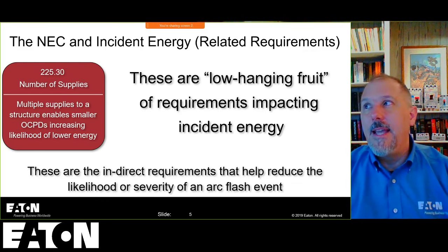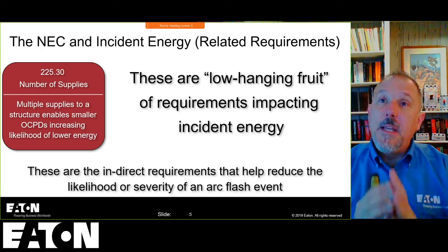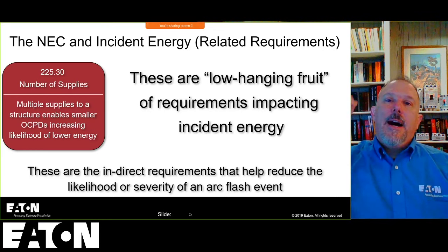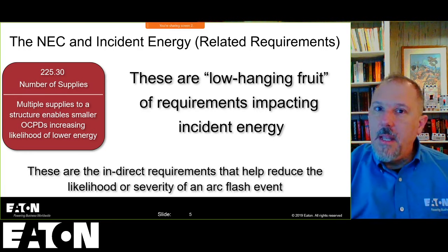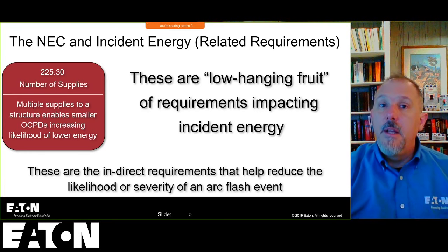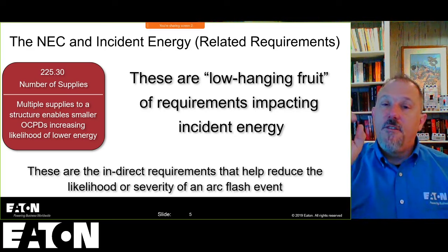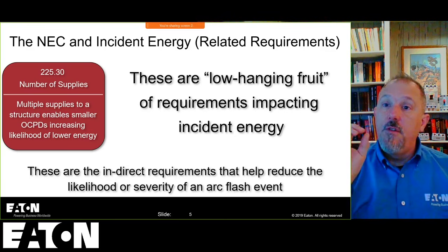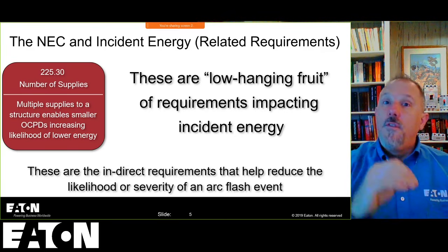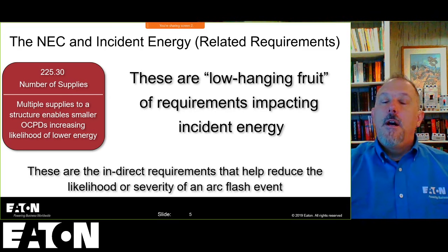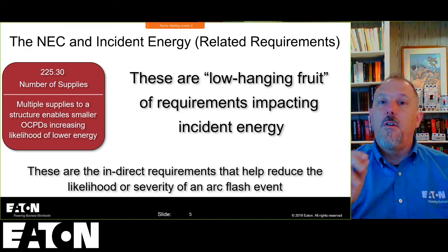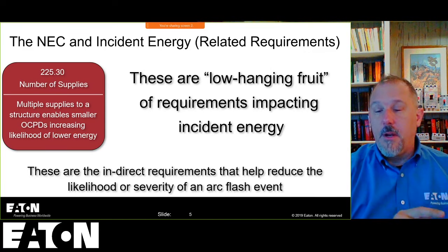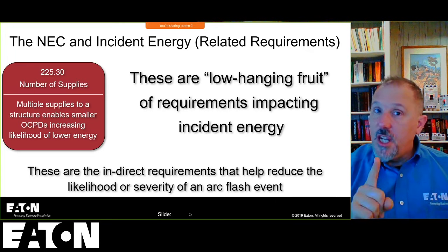Now you'll say, well, Tom, you've got to be careful, because 1200 amps worth of feeder conductor has a different impedance than 2 600 amps worth, and the fault currents will be much lower because you've increased the impedance with a smaller conductor. And that lower fault current that results could even be more difficult for the 600 amp breaker. But I'll take my chances on that one.